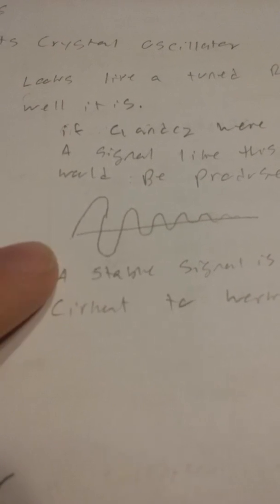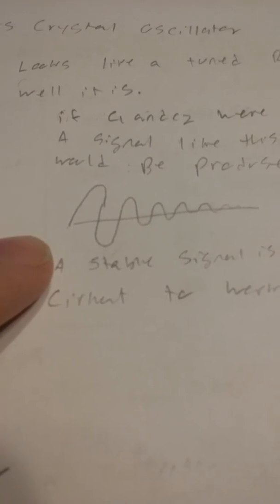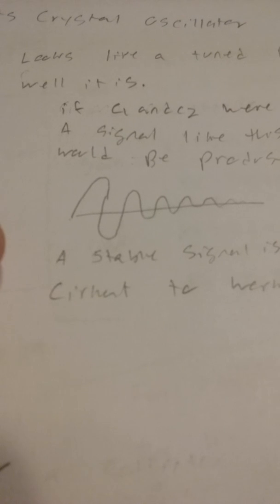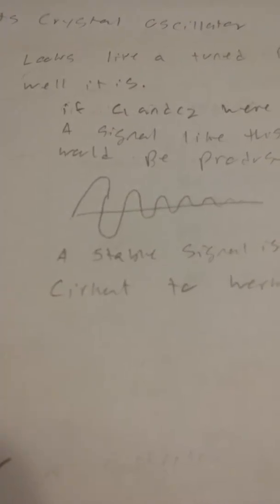And this is what our circuit would look like. Got our frequency, but the amplitude is unstable because there's resistance in the circuit, which is where our emitter follower comes in. So I drew it out so that it didn't have the feedback circuit in it. And we can see here, IB is 25 microamps. IC is 7.58 milliamps. IE is 7.61 milliamps.